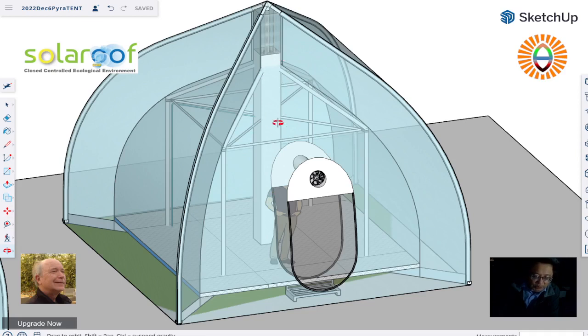So there's negative pressure in this portion, right? Then if there's no screen, the soap bubbles will be sucked in right away when they reach the edge. But if there is a screen, it tends to give surface tension, forcing the foam to go upward until it fills the entire cavity.